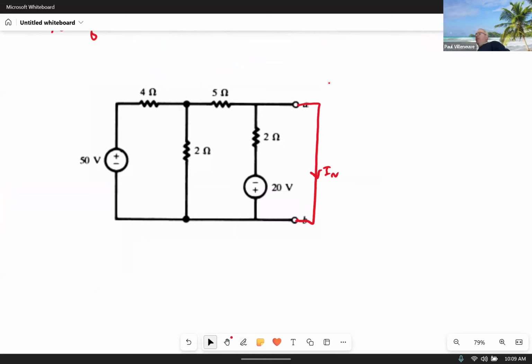And this is where we have to be careful. If we were to do nodal analysis over here, we really are setting ourselves up for danger because we know that that voltage would in fact be equal to 0, right? So it can complicate things a little bit when we're using nodal analysis for short circuits. We could solve for the node voltage here, but we only have that one nodal equation, right? So it can be a little bit fussy.